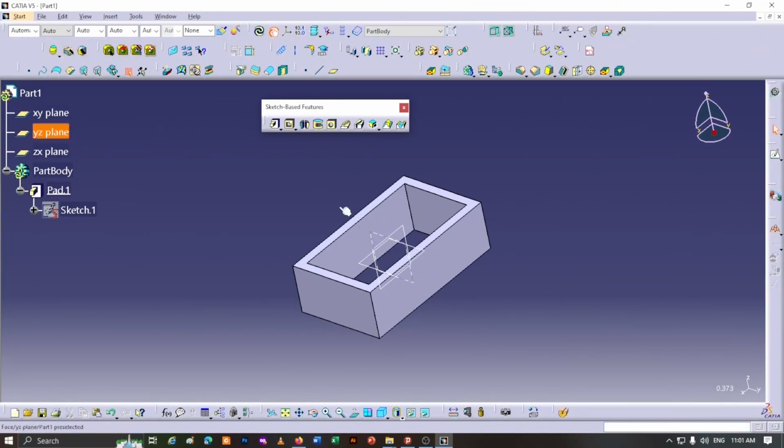Hello everyone. In the previous lesson we talked about the path command. With this tool we could create a solid volume. After creating a volume, we may want to cut some parts of it. By cutting from the solid volume, we can remove the cut part. To do this, we use the pocket command. The method for using this tool is exactly like the path tool.